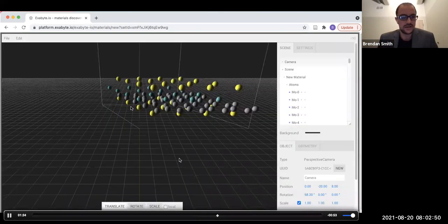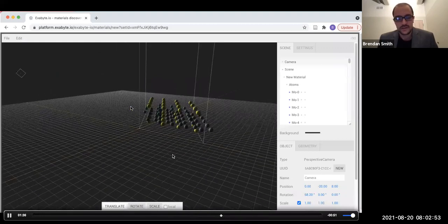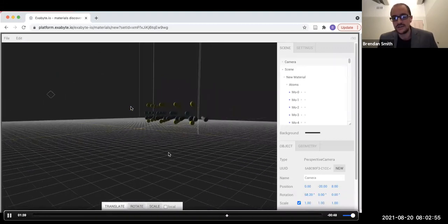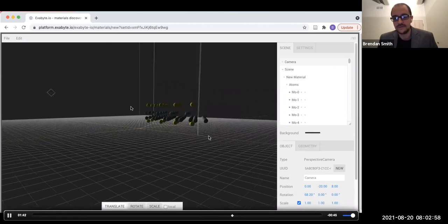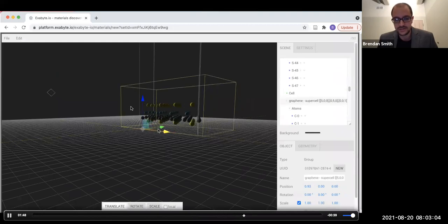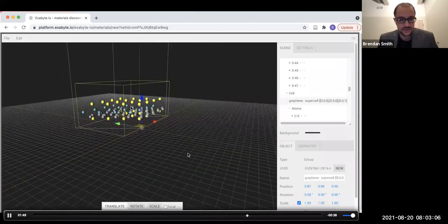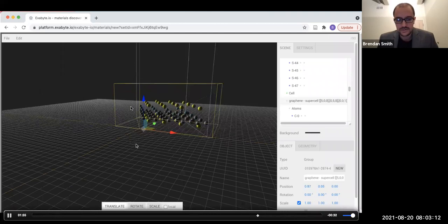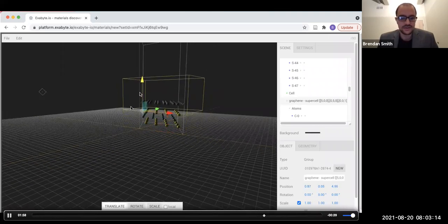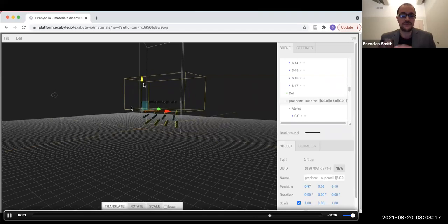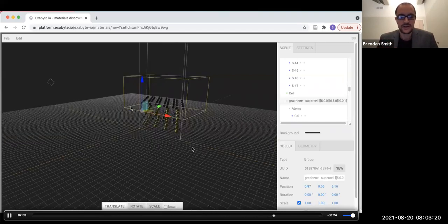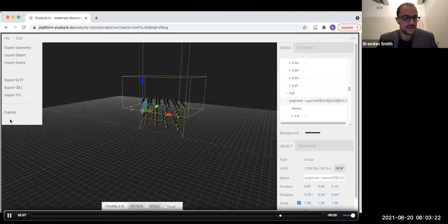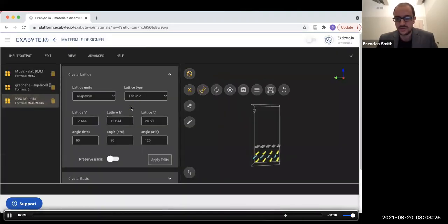Going into our multi-material editor, I'm going to simply use the edge of the unit cell as a way to place the graphene atoms. I scroll down and select the graphene system, and I simply translate it into the cell, using the edge of the supercell as a guide. When I'm trying to figure out the interlayer distance, this can be quite challenging. What I like to do is envision space-filling models of the material and think about where they might be. I'm satisfied here, so I'll go to exit, click on my new material, toggle the bonds, and you can see this nice interface we just made.